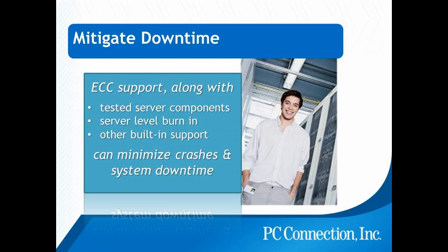100% of our memory for servers goes through these burn-in chambers. They go for 24 hours at extreme temperatures, extreme voltages, and basically we wear 3 months of heavy server use onto the module in that 24 hours. And so if it's going to fail, it's going to fail here at our factory first before it ever ships out our door. So these extra tests and these extra burn-in things that we do on these modules are just part of the feature set that you'll be able to rely on for a server class DIMM.